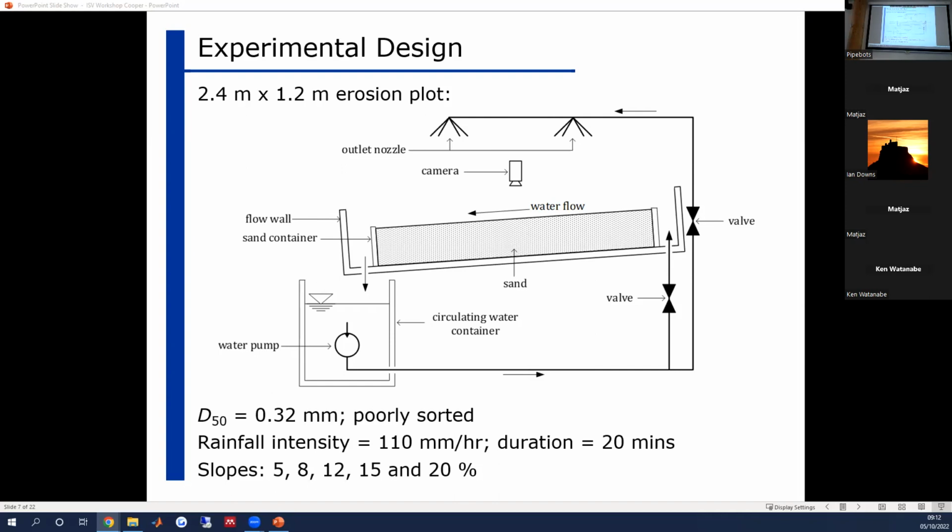And we repeated that for 5 different slopes so we could generate different topographies. And we used a local soil to Liverpool, so that the soil had a D50 of 0.3 millimeters, and we had a GoPro camera and a white light source for doing some surface PTV, and we seeded that with buoyant particles.